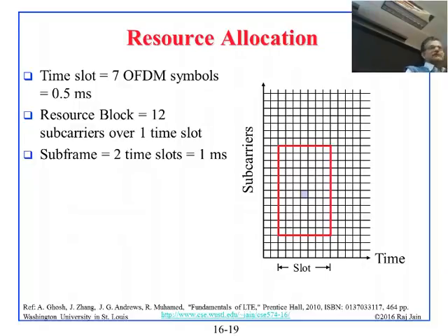Okay, so the question is whether it is better to go in time or better to go higher. If I need more, better to go higher in time or better to go higher in frequency? This is a very interesting question. On the downlink, it doesn't cost anything extra for the receiver to receive 1024 carriers. It is already receiving all carriers, right? So in the downlink, it will save the battery if the time is less, carrier is more.